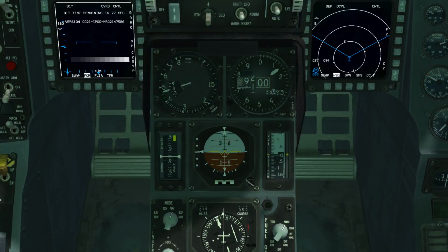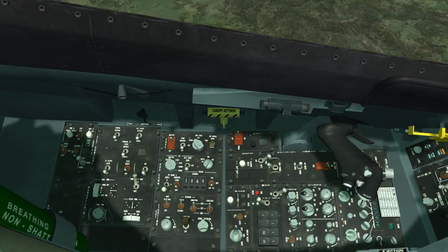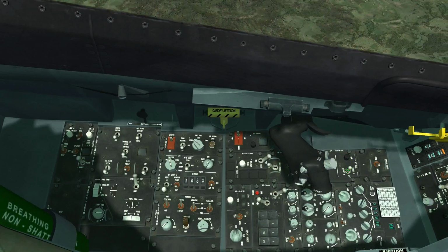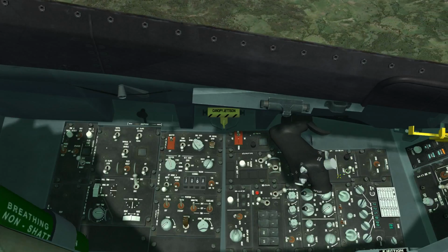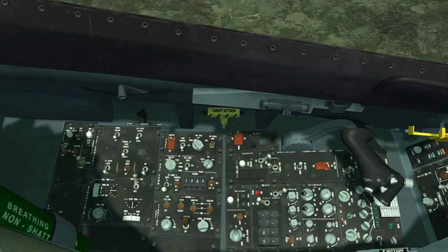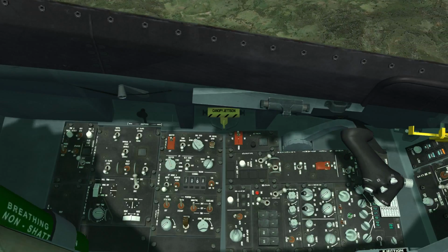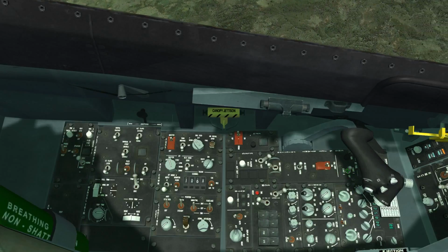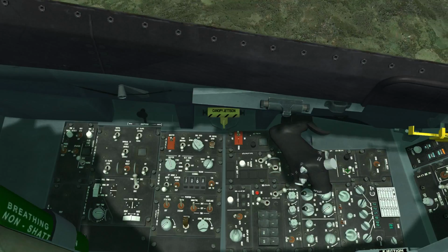Now, one additional thing is we pulled the throttle to idle, and then we did the JFS right click. If we do everything right, but we have the throttle all the way full forward in order to view the JFS start switch, and we tried to right click it, nothing would happen. So the throttle has to be back here toward the idle position.